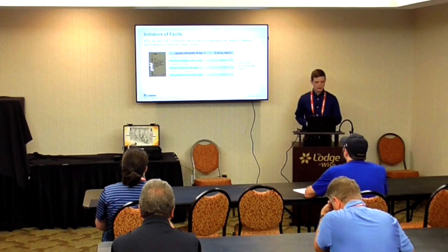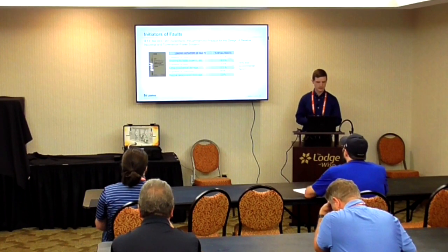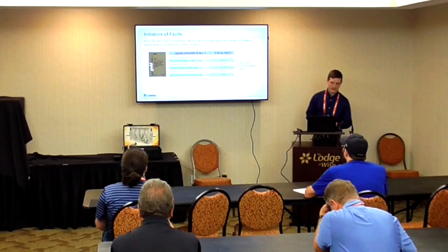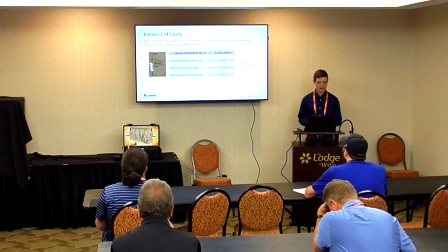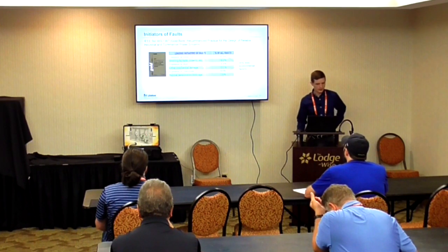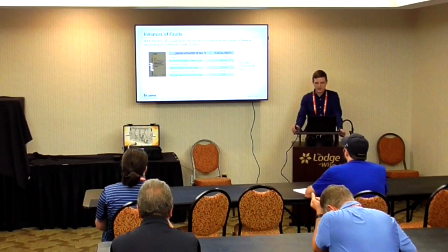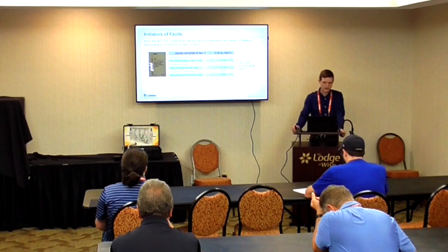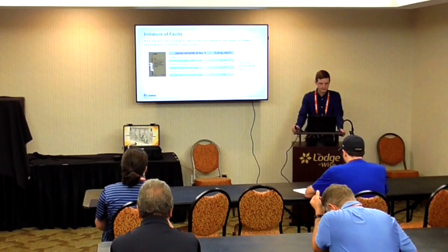So this is going back to the human error, just before we move on into some of these mitigation methods. IEEE, the Gold Book, or they used to be referred to as the color books, does cover some of the different statistics on how faults occur. 46% is just from the environmental factors, and then about 30% is caused by human or animal error. So going back to that top half of that hierarchy of controls, if we can eliminate about 30% of those risks, then why not?